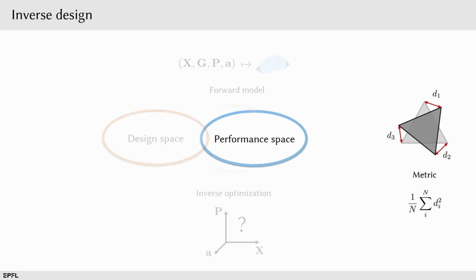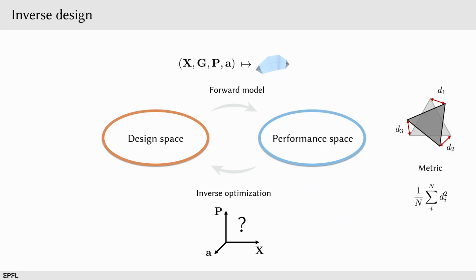If we want the surface to close flush, we then have to tweak the design parameters to make that happen. Let's assume we want to work just within the space of Monge surfaces, so we constrain our design space and performance space to Monge surfaces. In particular, this means that the planes and apex locating function values are off limits. We can't touch them because they are given by the construction already. And we have also seen how changing the generatrix doesn't help. So the only degree of freedom that we have left here is X, which is our directrix. That corresponds to our design space down there.